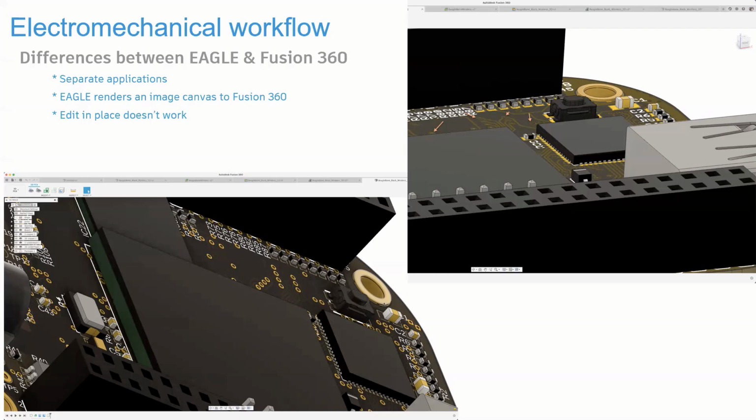They're not really functional. So that's one of the biggest changes that we have by adopting Fusion 360 as your program, because when you're moving between the 3D PCB and the 2D PCB within the Fusion 360 platform, each via, each trace, each pad is actually an independent extruded body that has materials assigned to it. Therefore, we could do really nice electronics cooling analysis on them as well, which is a topic for another webinar that we'll be addressing.